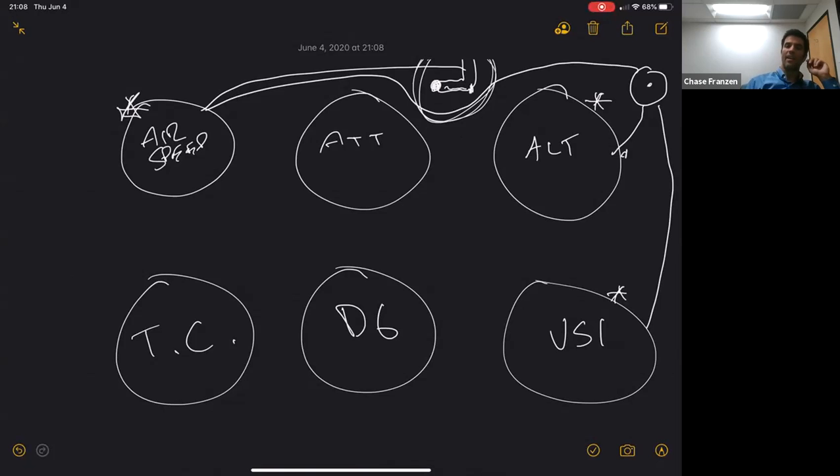Let's imagine for a minute that ice covers the whole pitot tube and it encloses the whole thing. So there's absolutely no air going into this system at all. What would happen to the airspeed then is you've got a bunch of trapped air. So the airspeed indicator would end up indicating like an altimeter. As you nose over the plane and start going down, you're probably picking up airspeed, but the airspeed indicator would actually show a descent. It functions like an altimeter, so the airspeed would go down. Similarly, if you start climbing in the airplane, the static pressure is changing, so your airspeed indicator will actually increase, because it functions like an altimeter, because that air is trapped.